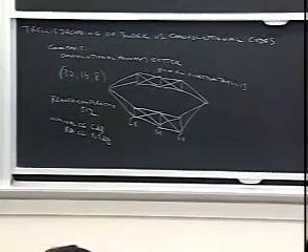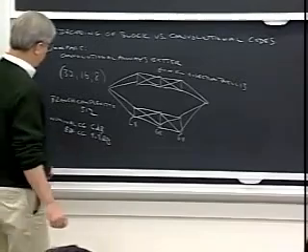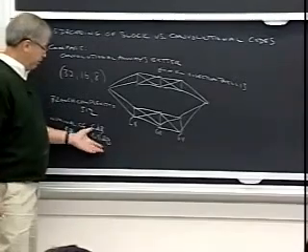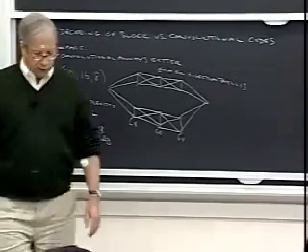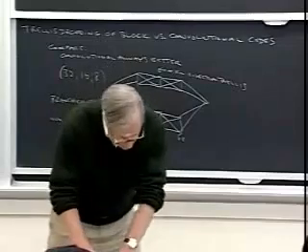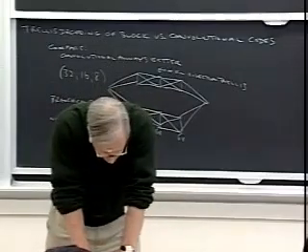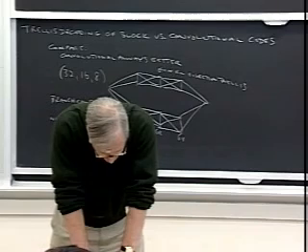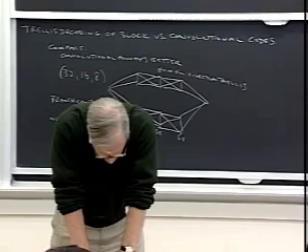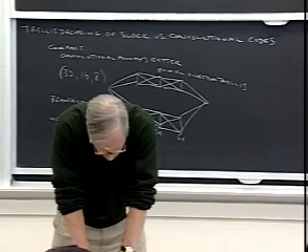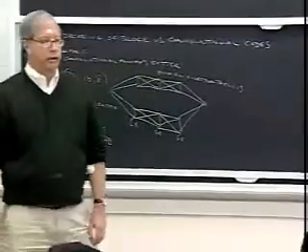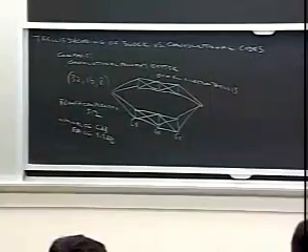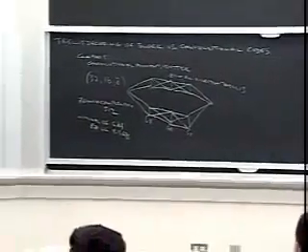Okay, so let's look for a convolutional code of rate 1/2 that has a coding gain of about 5 or 6 dB. And how far do we have to go? We actually only have to go up to a 32-state code, which has an effective coding gain of 5.6 dB. A 64-state code, we can get up to an effective coding gain of about 6 dB.